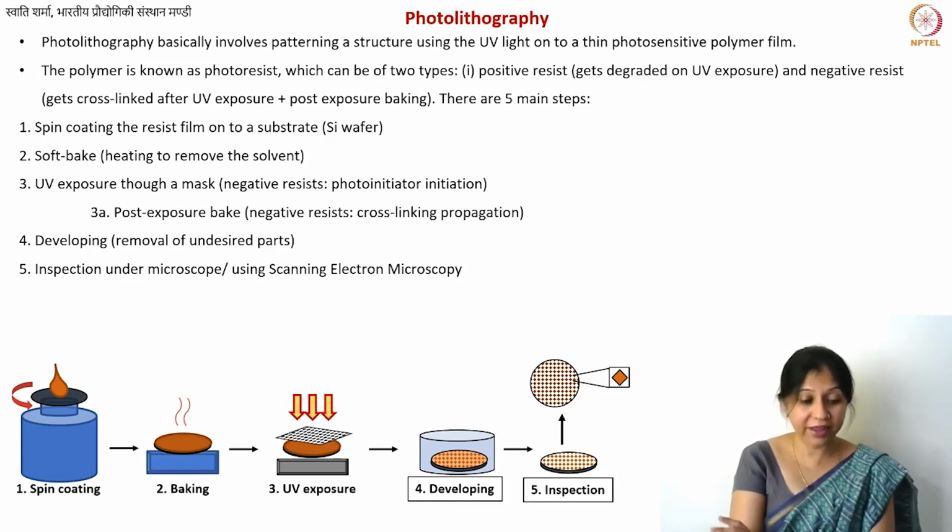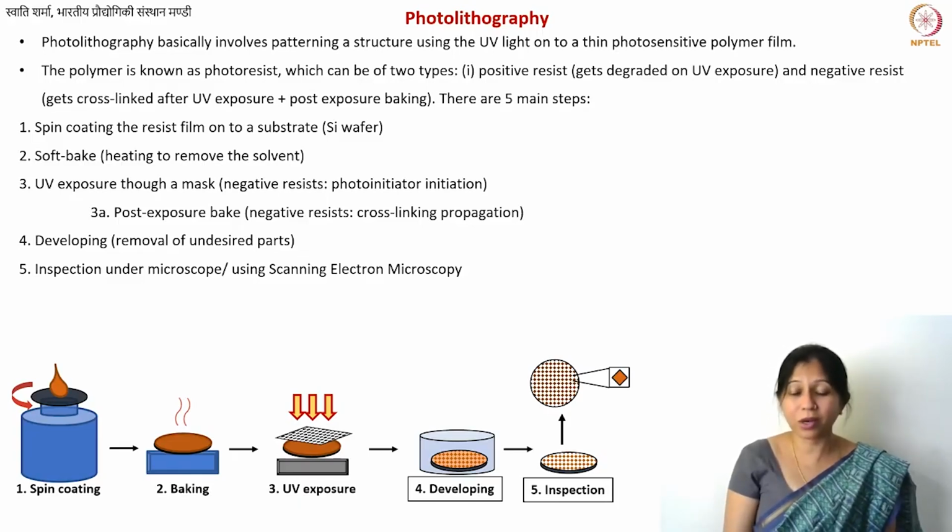Now, having said that, there are other polymers that have also been tried out, whether or not they yield glass-like carbon. You can read several papers. Okay, so the point is that the material should undergo coking, and in the case of microfabrication, these are specialized polymer resists. Sometimes you don't know the exact chemical structure of a resist.